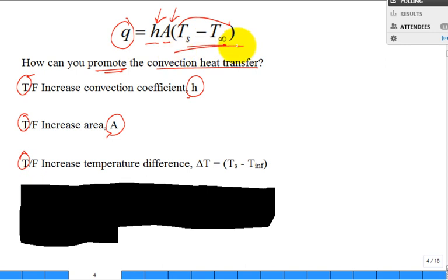When it's operating, I probably am stuck with this being the temperature that my engine wants to run at. Anybody know what's the typical thermostat temperature of the automobile that they drive? Have you had to replace one? You can get the OEM temperature, you could get the high temperature or the low temperature one. Always go OEM, what the manufacturer recommends. Around 200, about 180, 195.